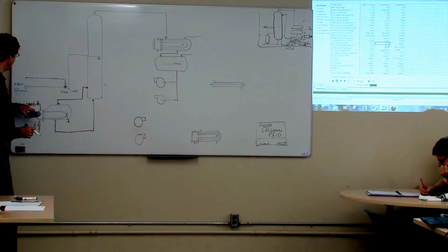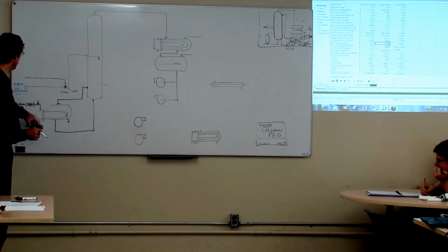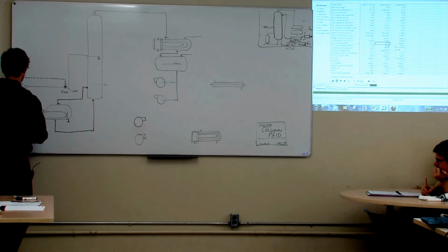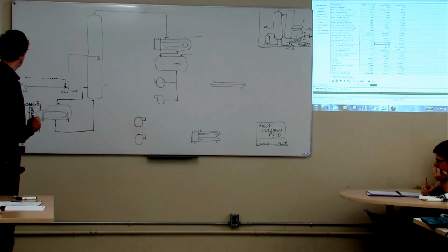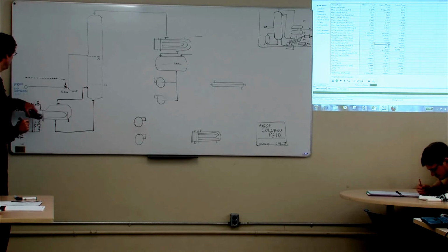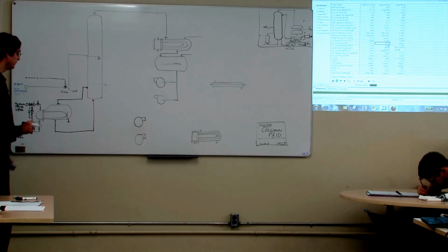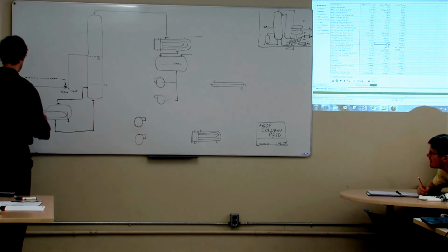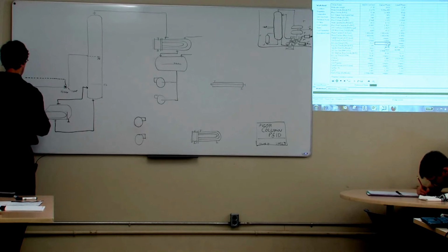And there's no guarantee that you've actually got dry steam coming through this system. So a lot of people will actually put another steam trap in upstream of the flow element. This isn't something that I would expect you guys to automatically know, but a lot of people will do something like that, just so that you've got relatively dry steam going into the heat exchanger.